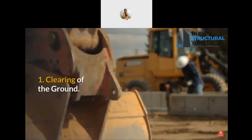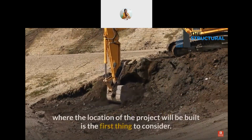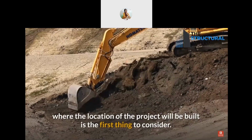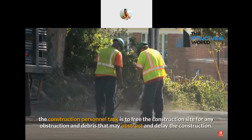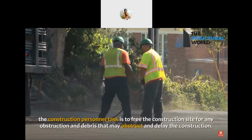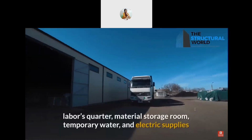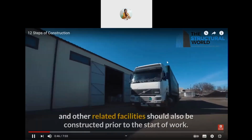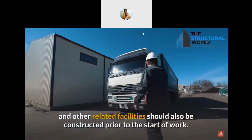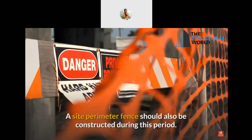1. Clearing of the ground. To begin the actual construction, the clearing of the ground where the project will be built is the first thing to consider. The construction personnel's task is to free the construction site of any obstruction and debris that may obstruct and delay the construction. The temporary facilities such as engineer's office, labor's quarter, material storage room, temporary water and electric supplies, and other related facilities should also be constructed prior to the start of work. A site perimeter fence should also be constructed during this period.